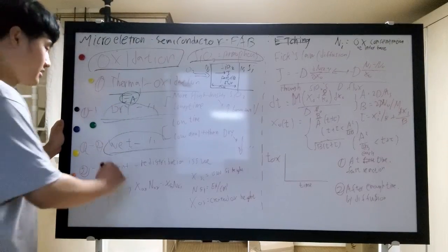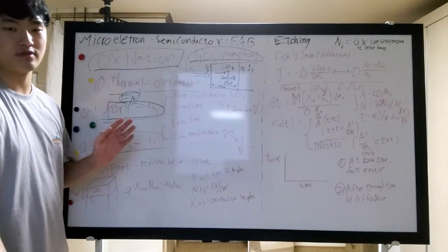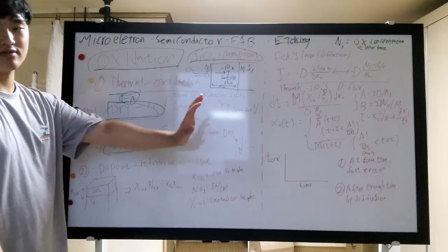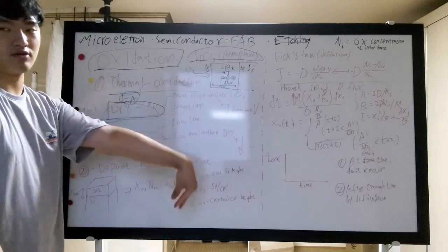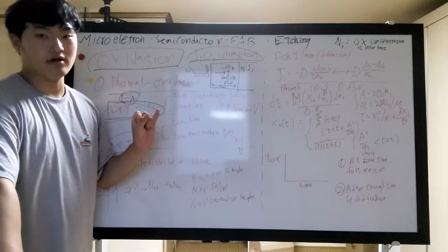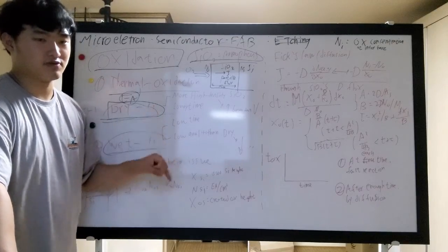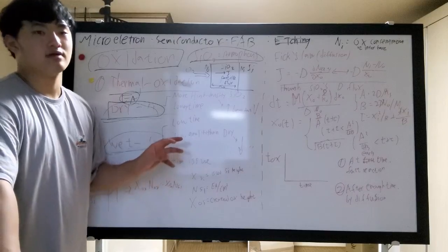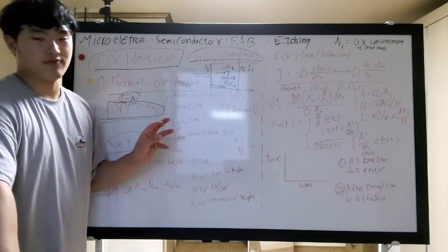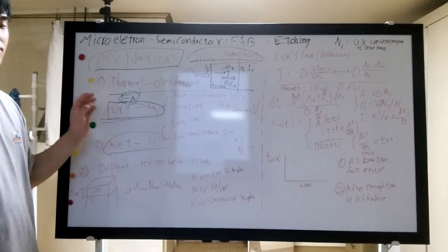For the dry process, it will take a long time since we use gas to put the oxide into the silicon wafers. But since it is injected between the bondings, the breakdown voltage or the formation will be more hardened than the wet process.